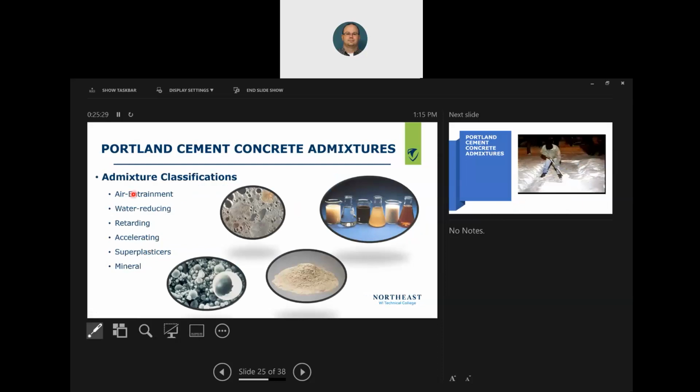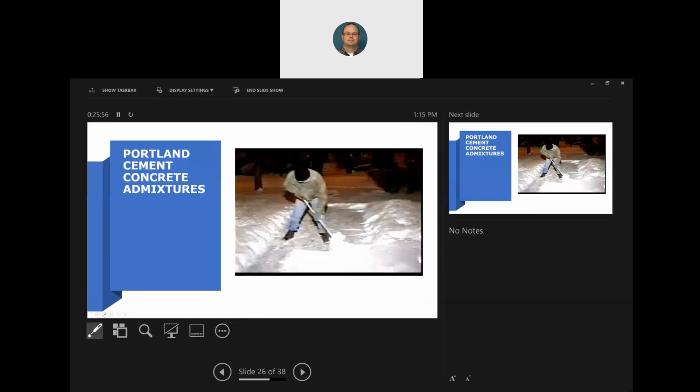So we have air entrainment. Remember we talked about that? Tiny little millions of air bubbles in there for freeze thaw. Water reducing, retarding, accelerating, superplasticizers, and mineral. We'll go over each of these. Mineral admixtures are chemicals, or sometimes there's mineral properties. All right, so let's go over this video.